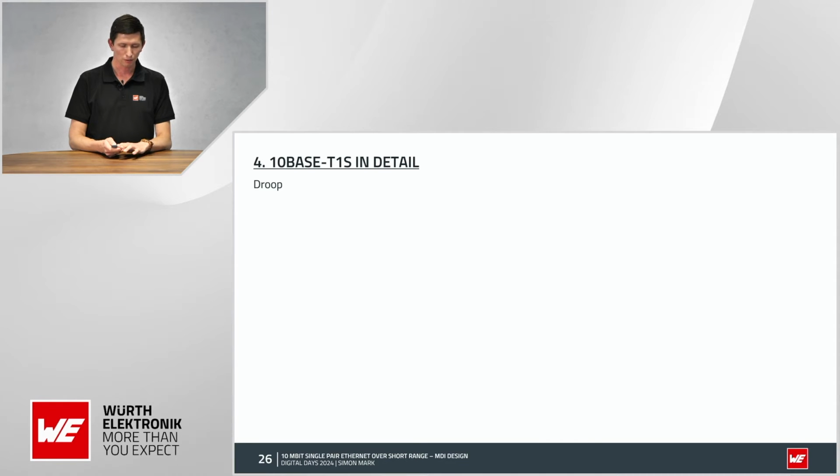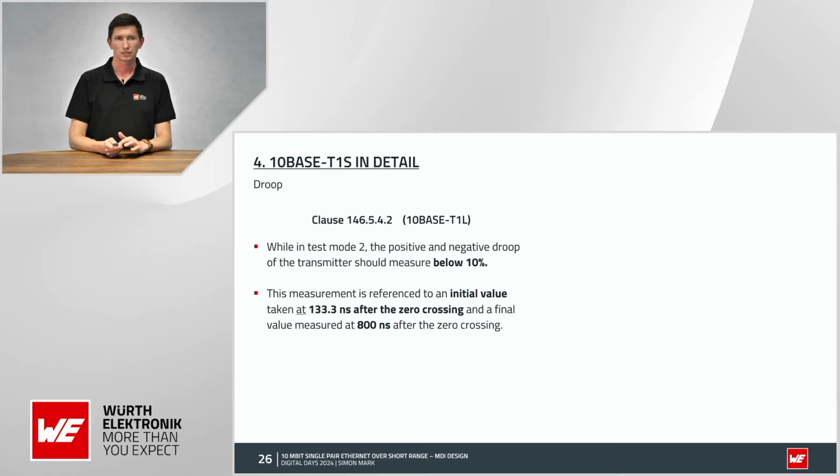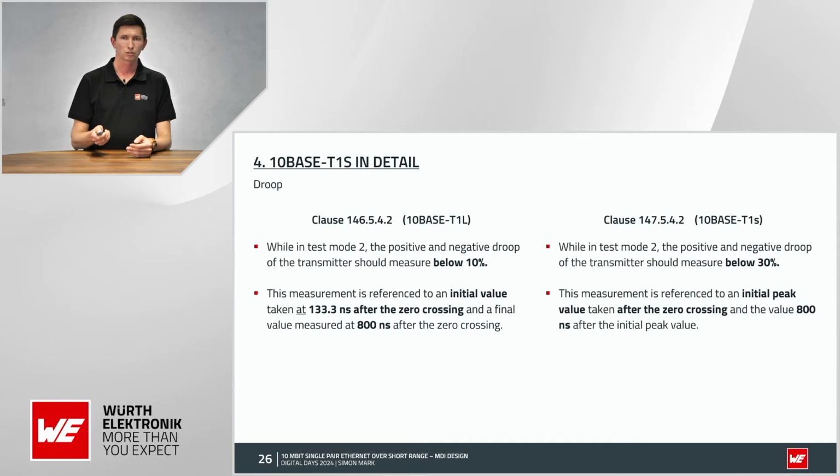An additional point is the droop. For the 10BASE-T1L, it is mentioned that the PHY in test mode will send several signals, and the droop, if you measure it, should be below 10%. This is the explanation for the droop for 10BASE-T1L, and for 10BASE-T1S, it should be maximum 30%.